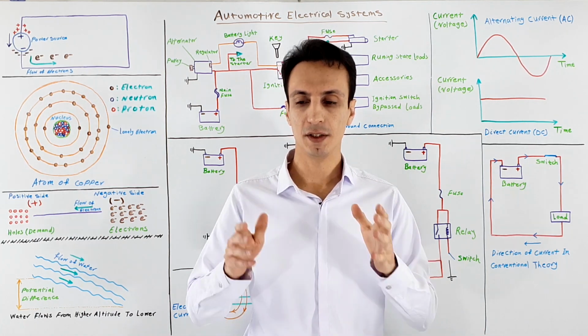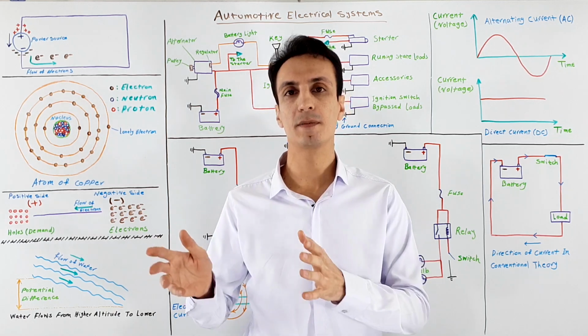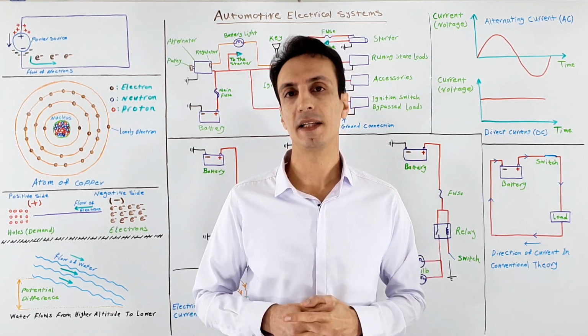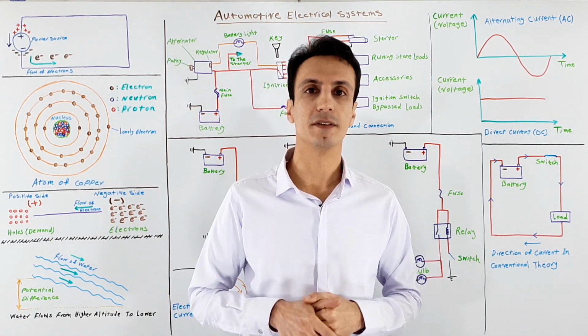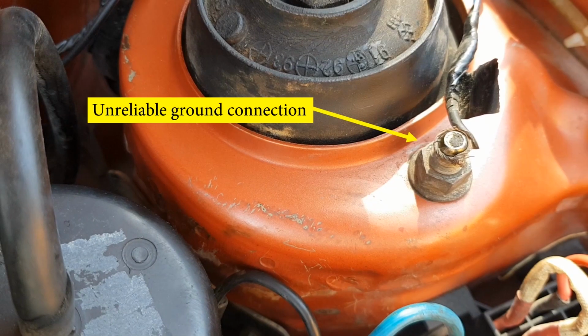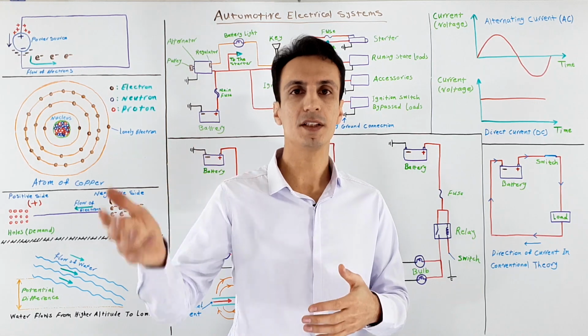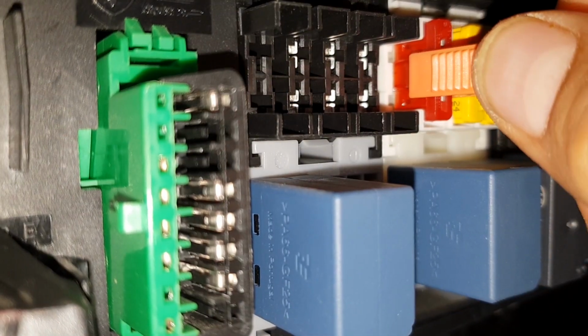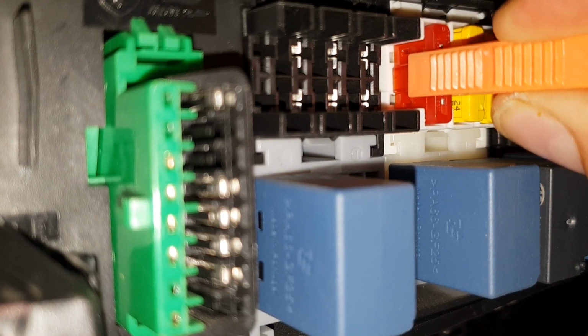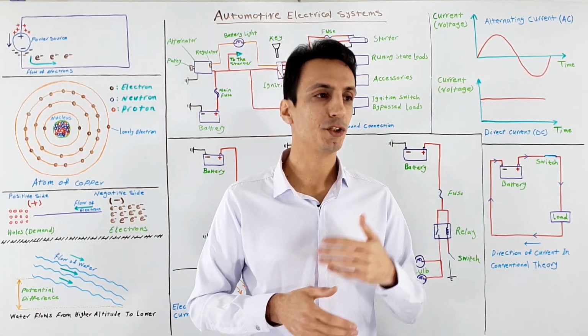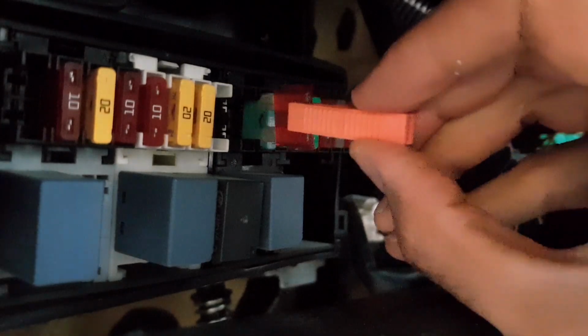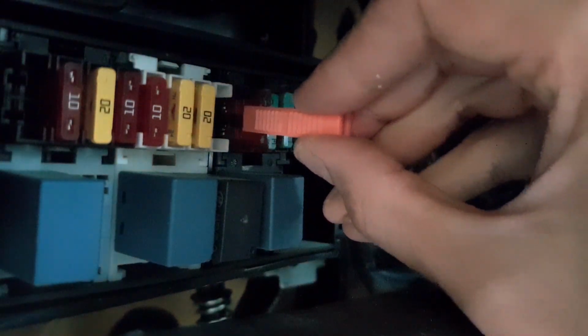For these issues, you can refer to circuit principles that I already explained, and very likely you can find the reason. Sometimes a loose ground connection is the cause, or maybe a fuse under the dash or in the engine compartment fuse box has blown. But always be cautious about the fuses when you want to replace them. The reason that the fuse has blown can be a short to the negative side, so when you insert the new fuse, it makes a spark and blows immediately again.